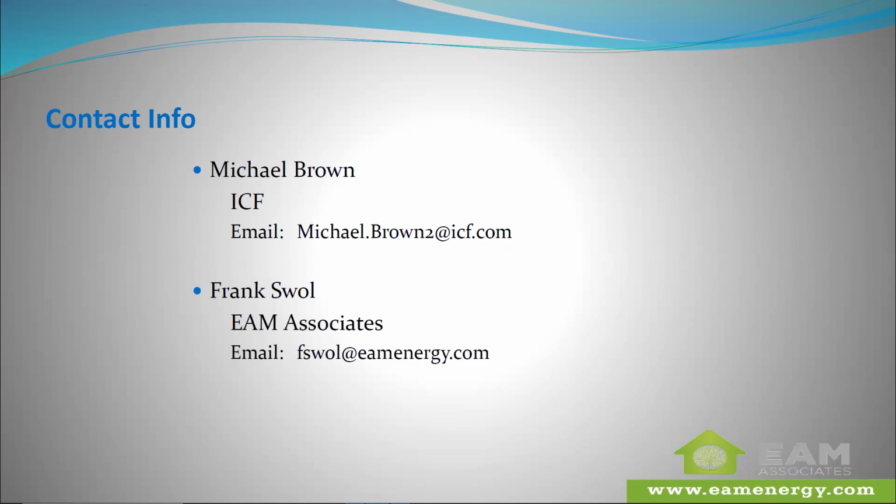And if there's going to be a later webinar on the HVAC grading standard 310 from ACA, it actually has a requirement that the infiltration rates in the design are within a tolerance of 2 ACH50 to the actual home. So if you measure 4 ACH, in order to get grade 1 HVAC per that standard, the design has to be somewhere between 2 and 6, so plus or minus 2 ACH. That standard does establish a tolerance for that.